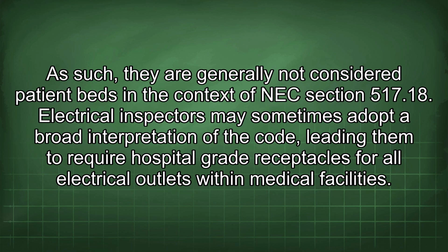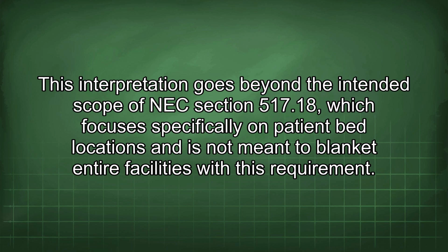Electrical inspectors may sometimes adopt a broad interpretation of the code, leading them to require hospital-grade receptacles for all electrical outlets within medical facilities. This interpretation goes beyond the intended scope of NEC section 517.18, which focuses specifically on patient bed locations and is not meant to blanket entire facilities with this requirement.